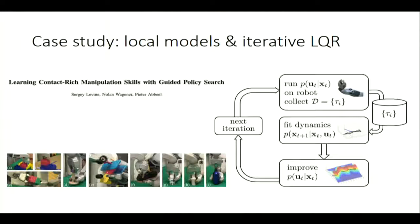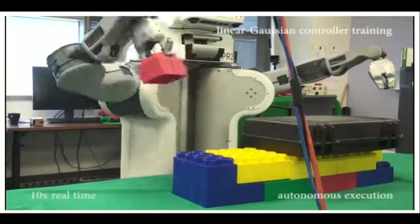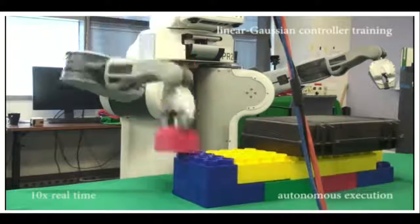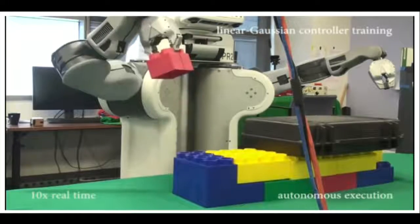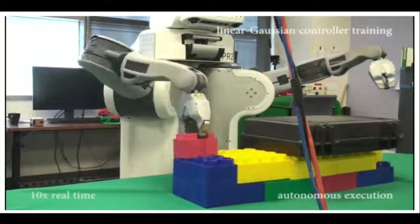So just to conclude, in the last minute, I'll show you one last case study for today's lecture, which is actually using this method to control some physical systems. This is basically the algorithm that we've derived with local models, and we can see here the learning process. This is a robot that, when it moves its arm, every five trials refits local linear models at every time step to those 5 trials, in this case using a Gaussian mixture model global model, updates its policy using the KL divergence constraint formulation, and then executes the new updated policy. So every 5 trials it's doing this. And in this case, it's learning to stack these little Lego blocks.